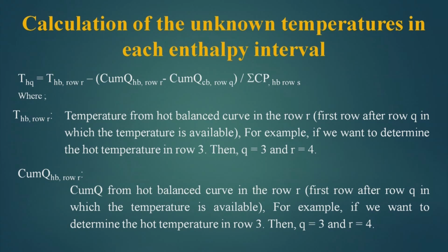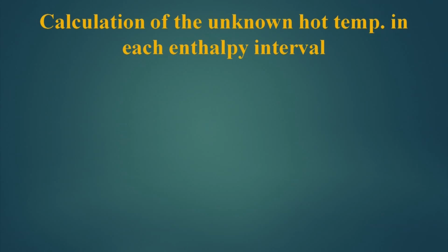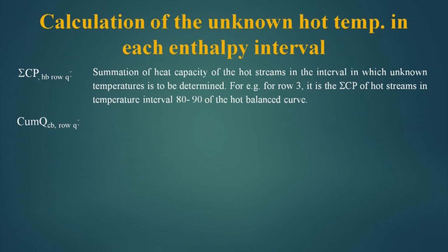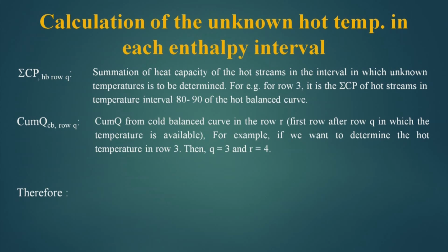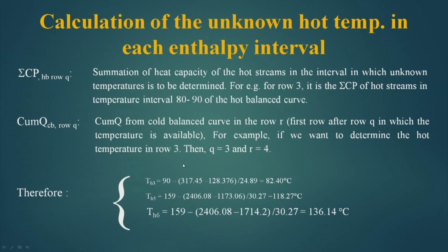These are the equations which are given for computation of this. We have explained clearly, and here it gives you the value of the different unknown temperatures of the balanced hot composite curve.